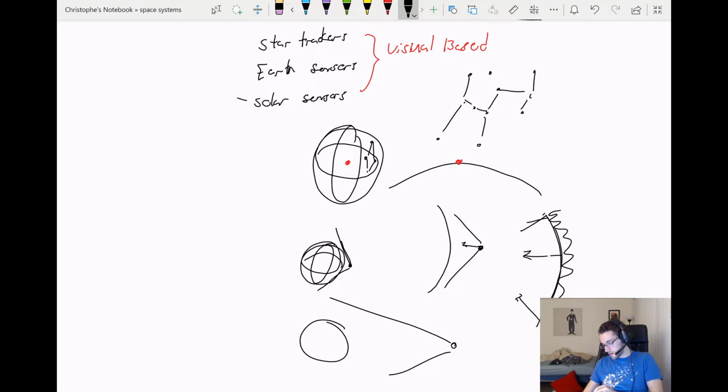Let's take a look at the top here, and that's our horizon from the top of our FOV. Those are all pointing in that direction, so you can piece together that all of these radial vectors are pointing towards the same center, and you can go, oh, look, that's my nadir vector.